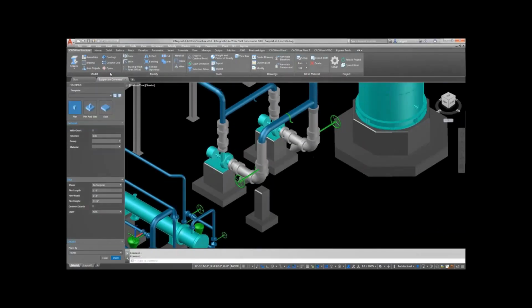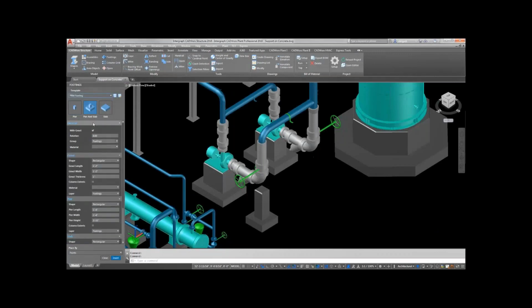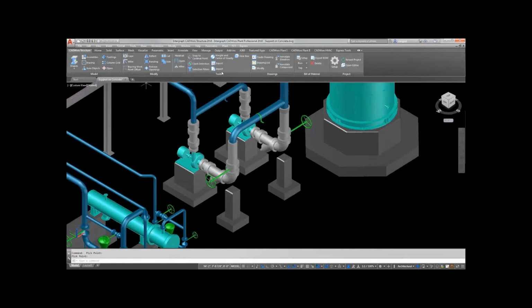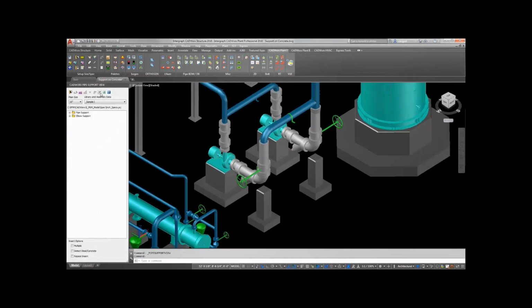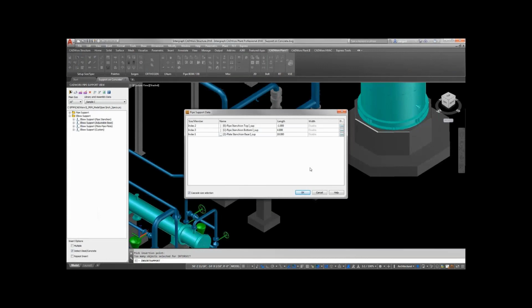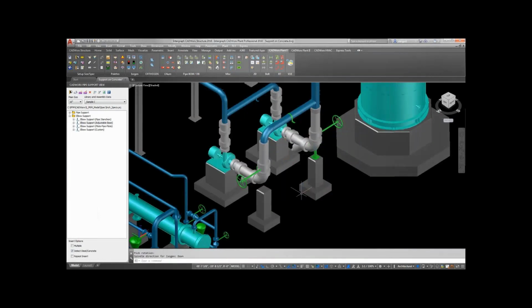Now updating the steel deduction, either to the steel or the concrete, when you're going to make the support. Now with the help of CADWorx Structure, I'm going for inserting a slab. With that, I'm going for attaching a pipe support to it. Through our pipe support library, choosing the pipe support by enabling the deduct steel or concrete option to it. Okay, so just select the elbow and then select the particular concrete component.